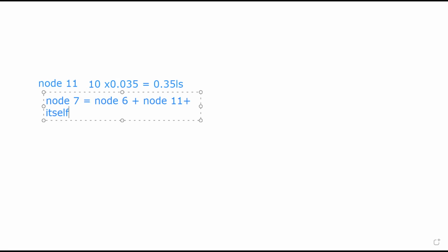So what is node 6? Are there houses connected to him? That's the next question. Okay. Look at the drawing. Yeah, there are houses. There are 1, 2, 3, 4. So if you are doing times 2, it will become 8.